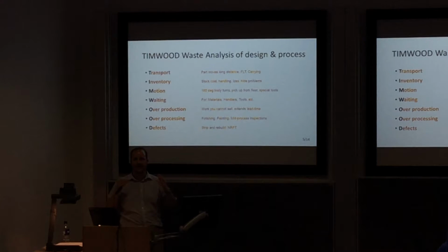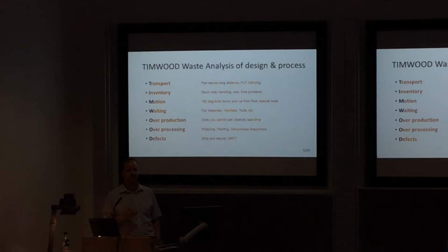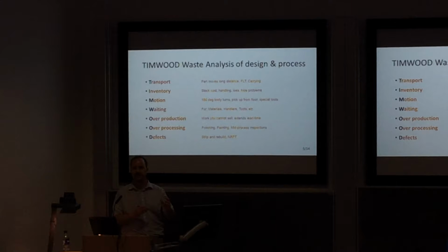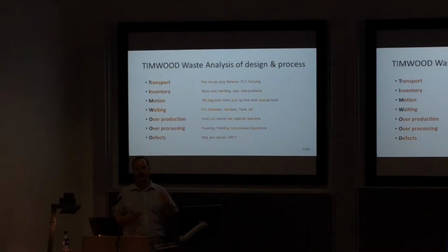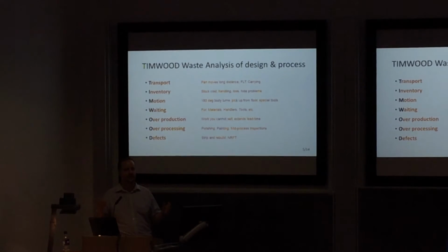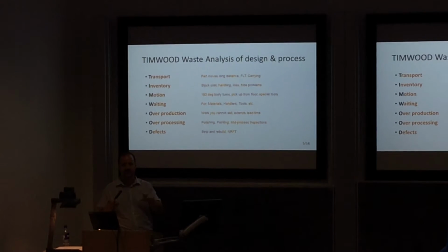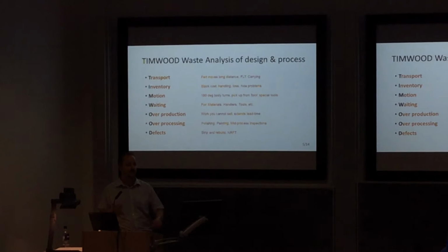It means having good materials, thick components, bits that are never going to wear out. In reality, in the modern workplace, though, that's considered to be over-engineering. If you have parts that are a lot thicker than they need to be, then you're spending too much money on your materials. If you have a feature which has got a tight tolerance on it, but it doesn't need to have a tight tolerance on it, then you're spending more money than you need with both the manufacturing, the machining, and the inspection process.